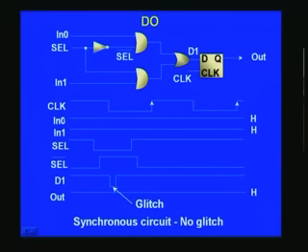Now let us consider a case wherein in 0 and in 1 both inputs are high. In such a case, what will happen to this circuit? Let us have a look. Let us say the select goes from high to low, as in this case, and naturally after an inverter this select bar will be the inverse of that. Here, and of course there is a delay here, and this gate delay is because of this inverter, and if you see the output here at D1, what happened?